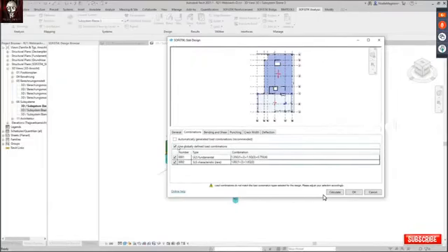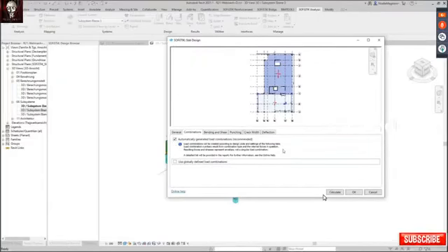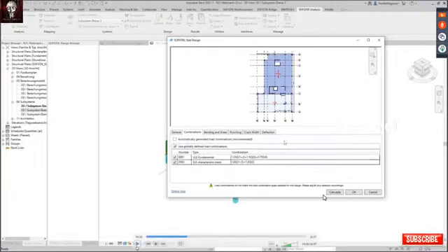Very important, in the newest version and service pack of analysis and design, you have this tab combination, which is allowing you to go between automatic combination, which are calculated and generated automatically by the software SOFiSTiK, or the global load combination, which you just defined into Revit. This has been implemented for all design tasks inside of Revit and can be used for all design tasks inside of Revit.